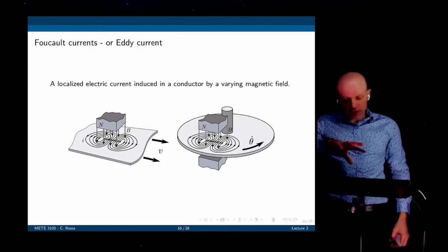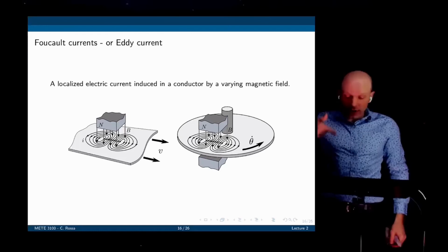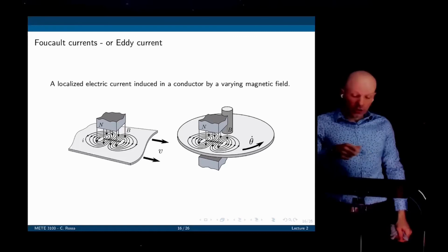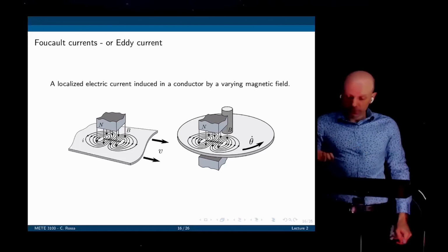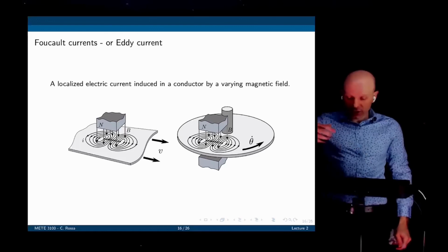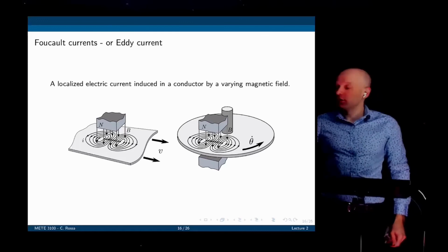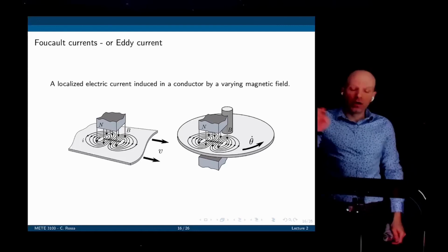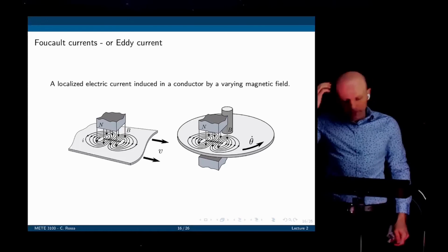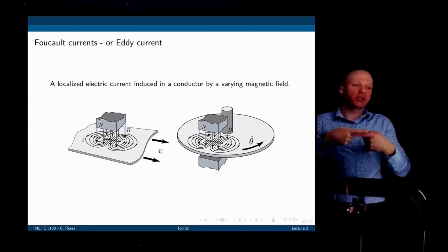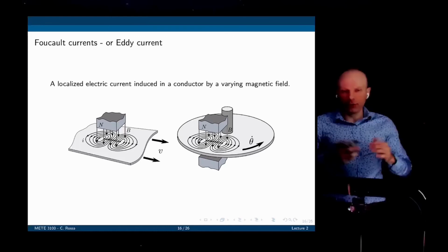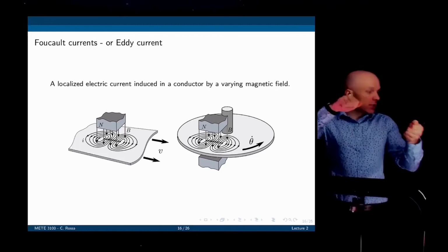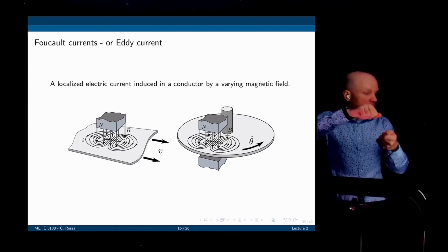If the material is conductive and is ferromagnetic, then eddy currents will establish. These eddy currents create their own magnetic field, and this magnetic field from these currents opposes further changes in the originating magnetic field. That is Lenz's law, that is the negative sign in dΦ/dt. Because of that, these two plates will be subjected to a force that will try to move them apart. And that's how a brake works. Because of that force, if you move the plate under the magnet, you will experience a force that is in the opposite direction to the velocity.